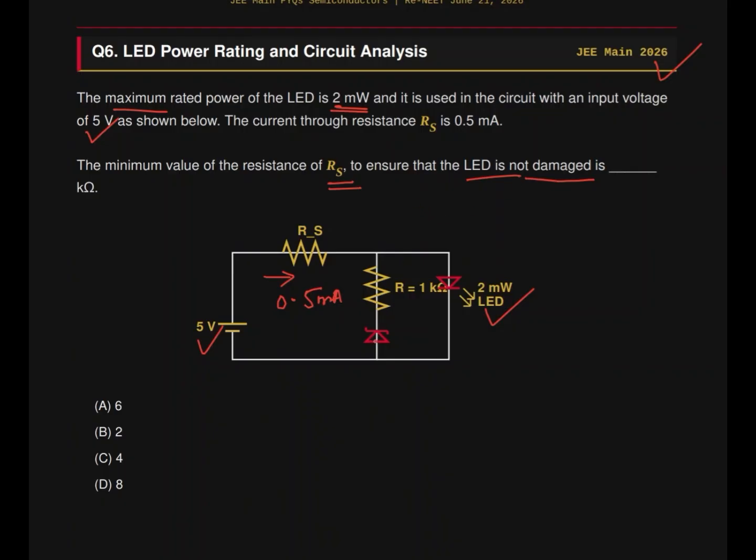Here, as you can see, I think this is wrong. This is not a zener, I think. This is just a diode, and this is reverse biased, right? So current will not flow in this direction, from N to P. So this branch is of no use actually. So the current will be flowing in this direction only, 0.5 milliamps.